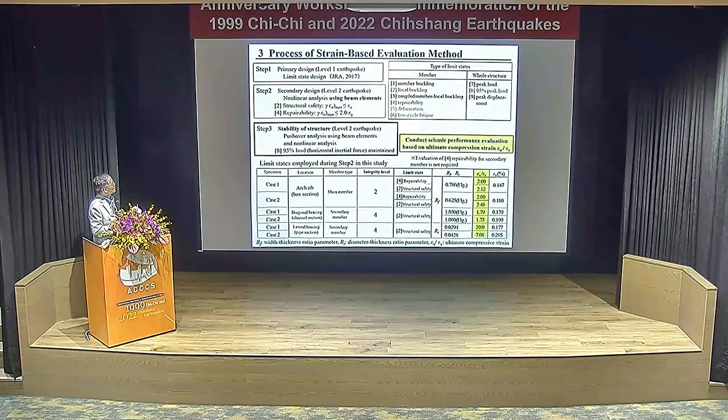And the process is usually, first, to perform a preliminary design according to level 1 earthquake, moderate earthquake. That's usually a limit states design.